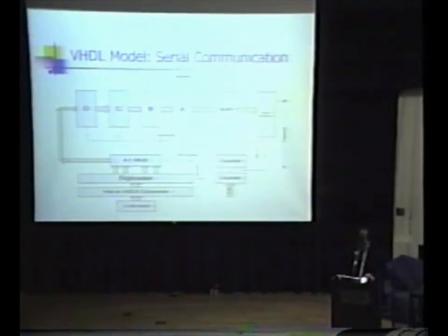The first block of VHDL that was needed was serial communication. Basically, the FPGA doesn't have any debugging capabilities on it, so I can't really see what's going on inside the FPGA. So I created this piece of hardware to send to HyperTerminal to tell me what's inside.